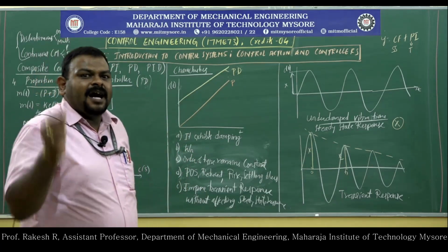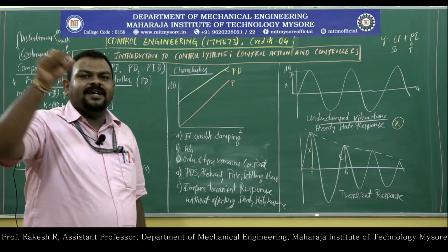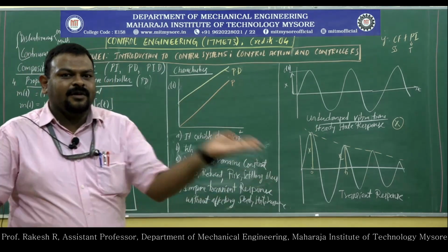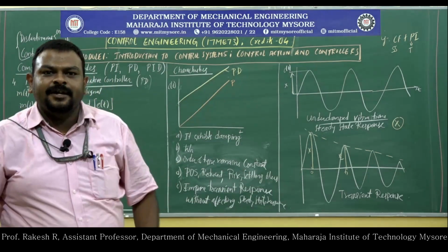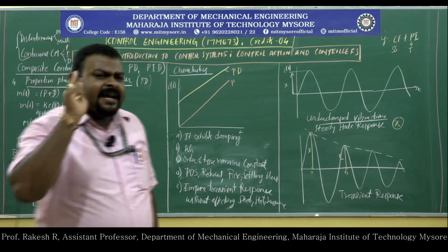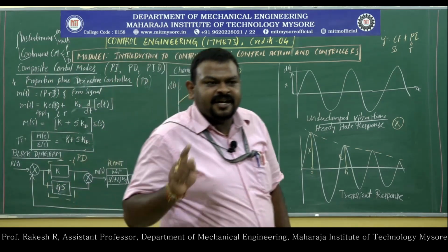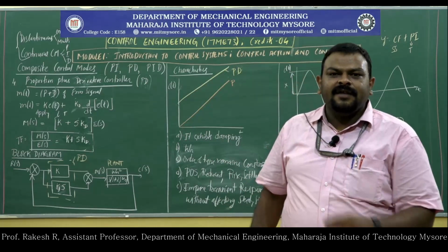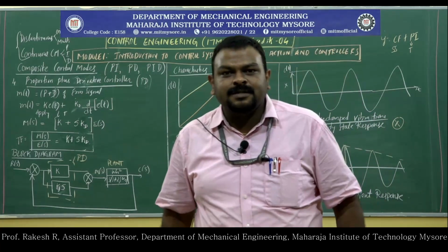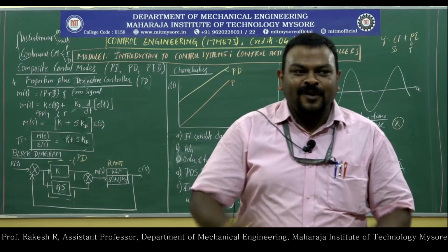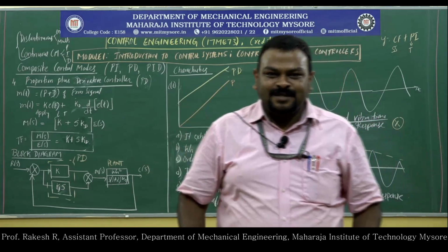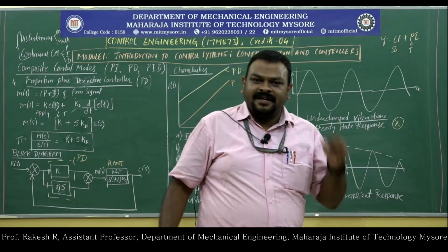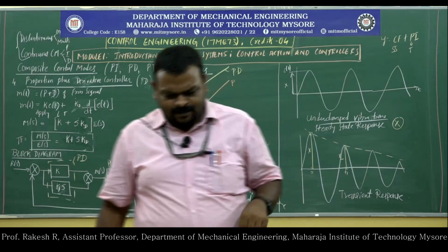Because of the advantages of PI controller and PD controller, both are mixed and the PID controller was developed. PI controller will improve steady state response, PD controller will improve transient state response, PID controller will improve the overall response of the system, and that is flexible in case of practical control systems.